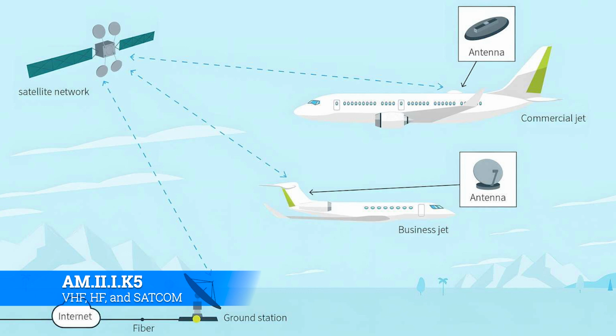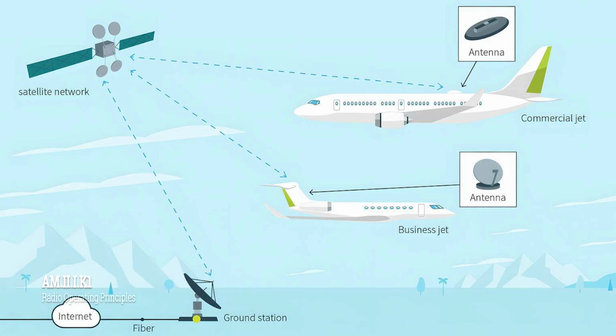That's all it really comes down to. Now, typically on satcoms, especially on older planes, you'll do almost like a text message kind of thing. You can talk verbally, but generally speaking, what they'll end up doing is sending text messages back and forth. The way things seem to be progressing, since computers can read text messages far easier than audio messages, it's becoming more and more the case that eventually you're going to listen to ATC and you won't hear anything because it'll all be text messages from one airplane to the next. Yeah, so that's SATCOM.